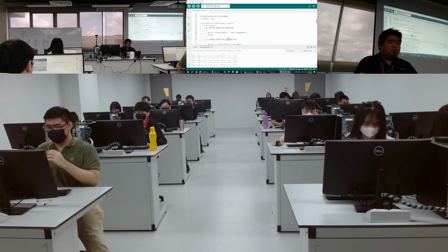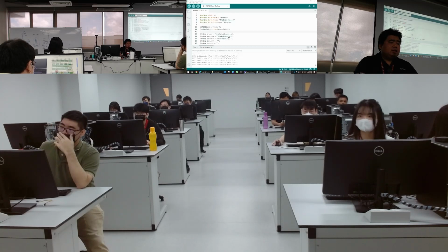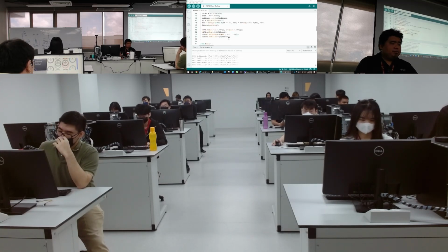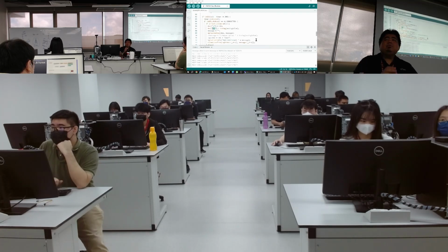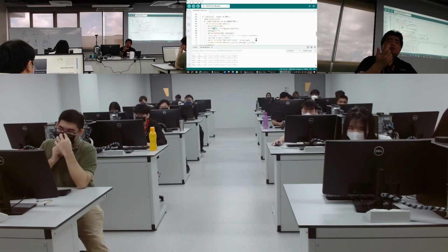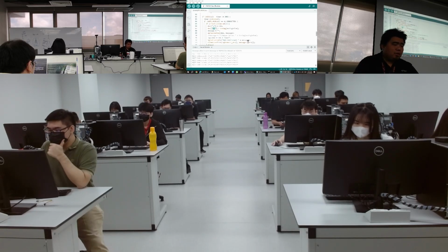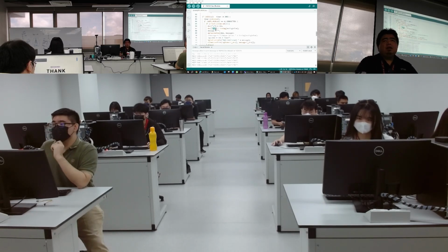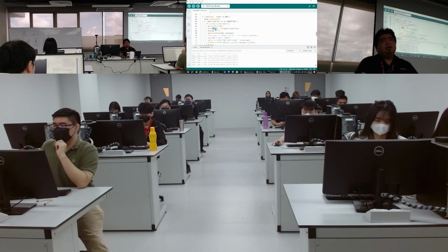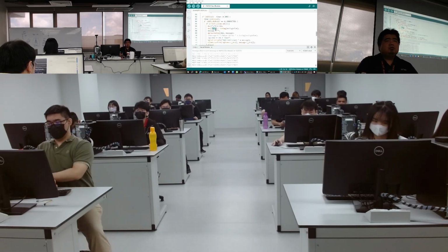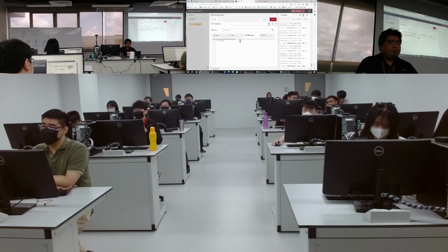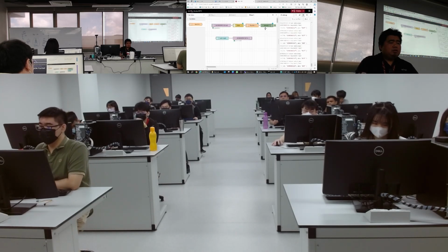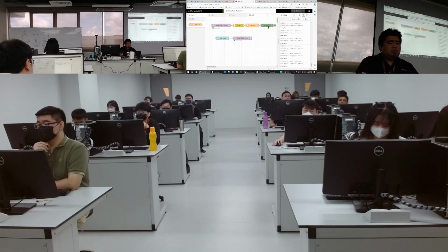Here make sure it's ADC, since we want the ADC value. If the name here were ADB, you should key in ADB; ADC1, then ADC1. But we want this value, so we call ADC. Then we try to deploy, and it's undefined.